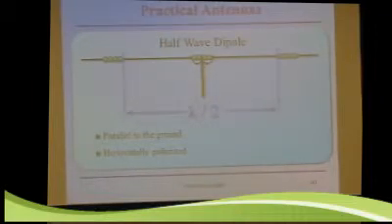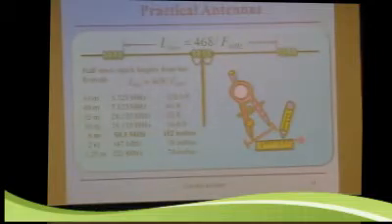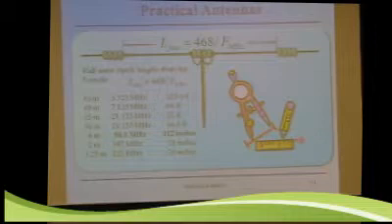That's really the antenna that most antennas should be compared to, because that's what most people can do. The big number, the one I remember all the time, is 468, because the length is 468 divided by the frequency in megahertz.